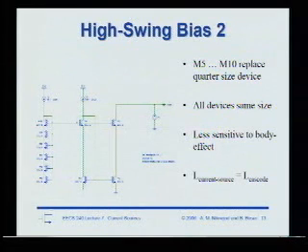Yes? Some of that body effect can be compensated. That's right. So the trick is that because the voltage from here is gradually increasing up to the full, let's say, 2 overdrive plus VT, these transistors are experiencing body effect. And so to some degree that matches the body effect experienced by this transistor. And so this is less sensitive to body effect. I mean, it's not perfect, but it's a solution. Okay? Questions or comments about that?